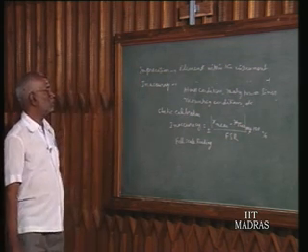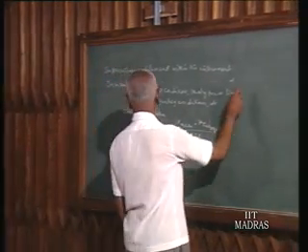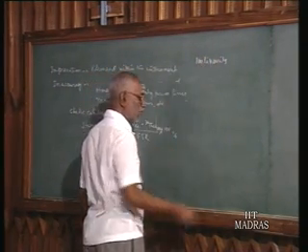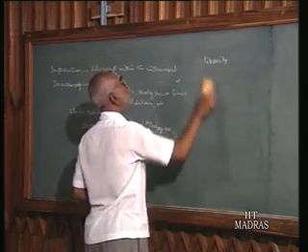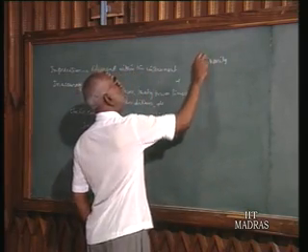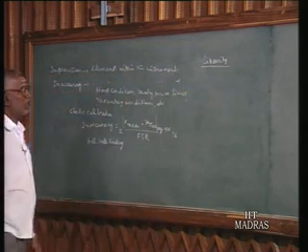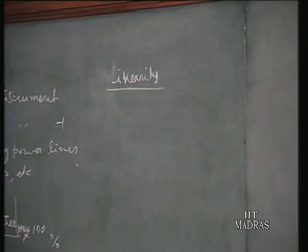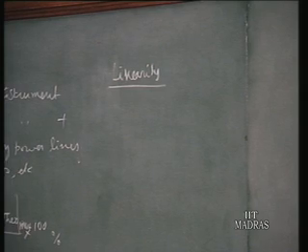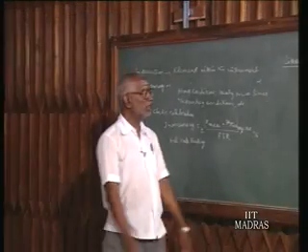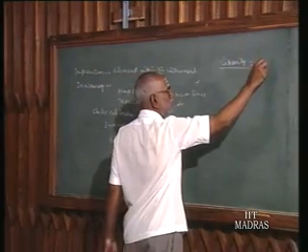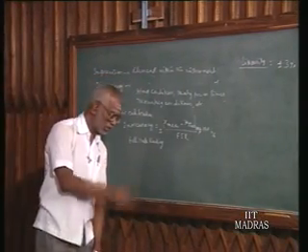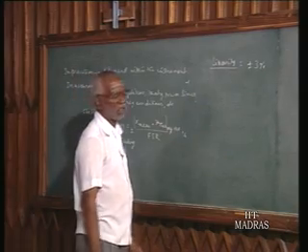So this is all about imprecision and inaccuracy. Next is nonlinearity. Actually, it is called linearity. As we have seen for accuracy and precision, the accuracy represents inaccuracy, and precision represents imprecision. Similarly, here the linearity actually represents nonlinearity. When we say linearity is equal to plus or minus say 3%, it means nonlinearity of the instrument is 3%, not linearity. So in the same way here also colloquially we are using the word linearity to indicate nonlinearity.